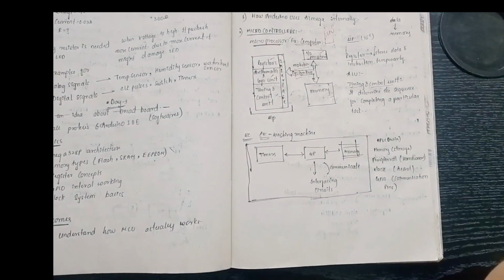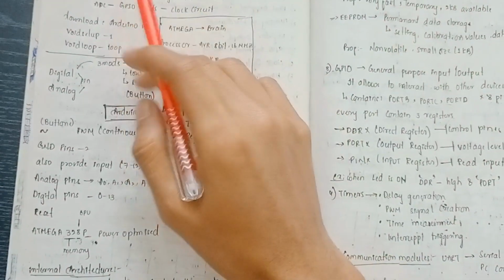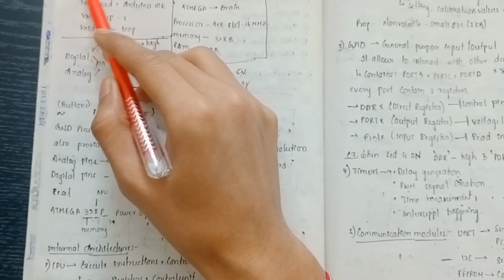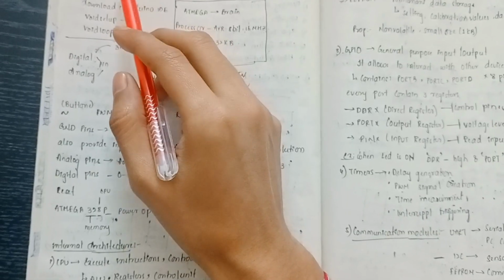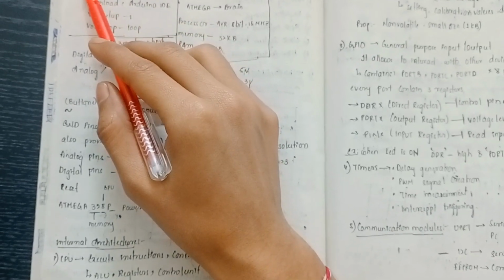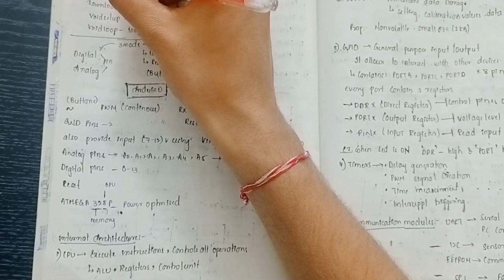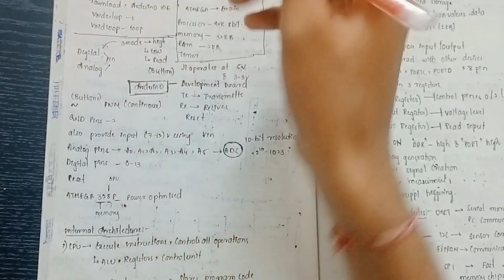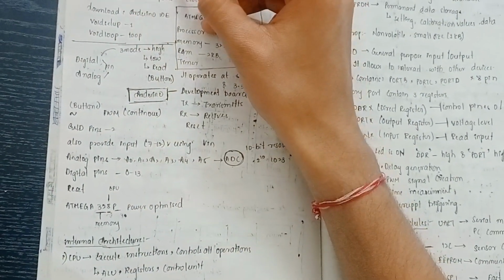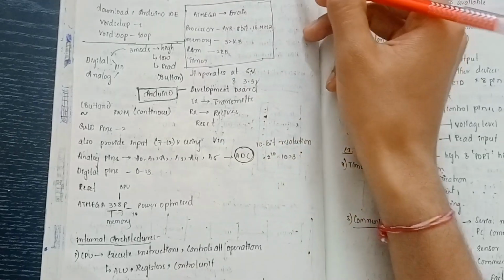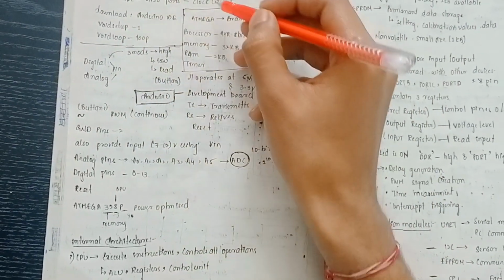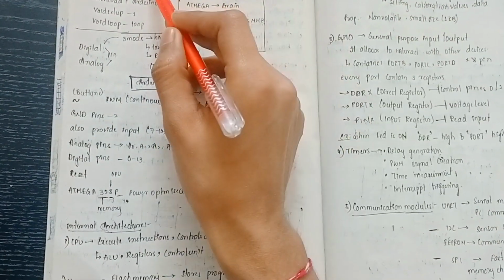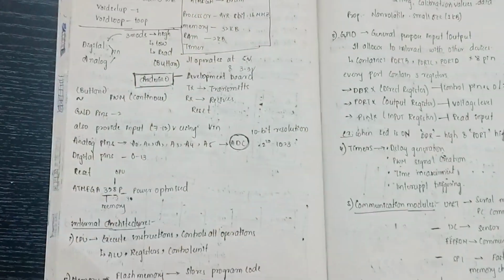That's about microprocessors. So here comes the most interesting topic: ATmega and Arduino internal hardware. ATmega is considered the brain of the Arduino Uno or any other Arduino system. Generally here we use the ATmega328P in Arduino Uno. ATmega consists at basic level of a CPU, flash memory, SRAM, EEPROM, timers, ADC, GPIO ports, and a clock circuit. These are the memory devices which are assigned with the ATmega microcontroller.